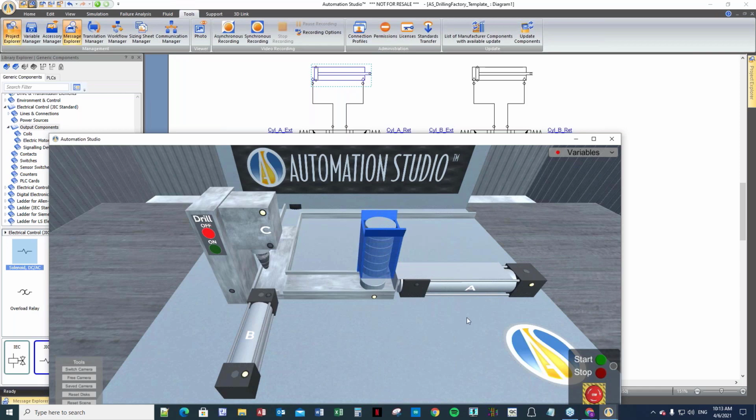So I can use this variable, and relate it to the output position variable of the cylinder over here, to make this cylinder move at the same pace, at the same speed as this cylinder when I go into the simulation mode of Automation Studio with the real devices. So the only thing I need to adjust is that the range this variable changes matches the one this variable changes over here.